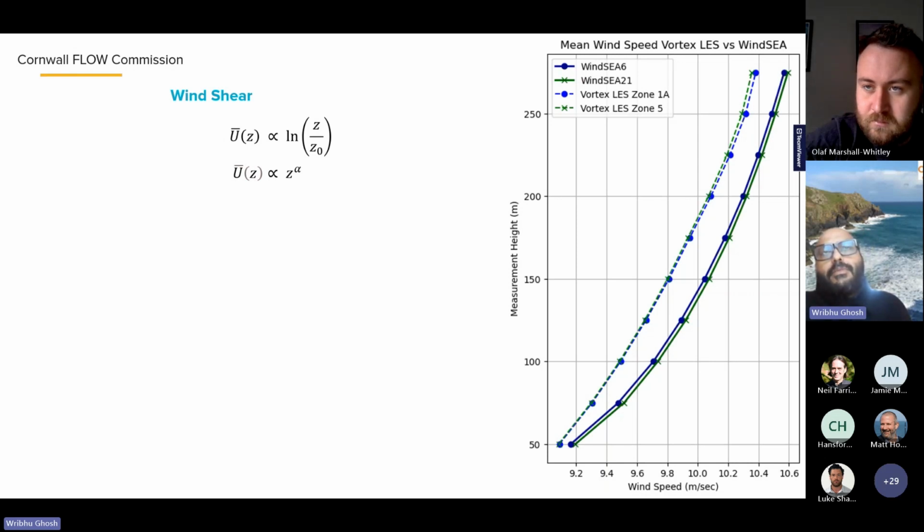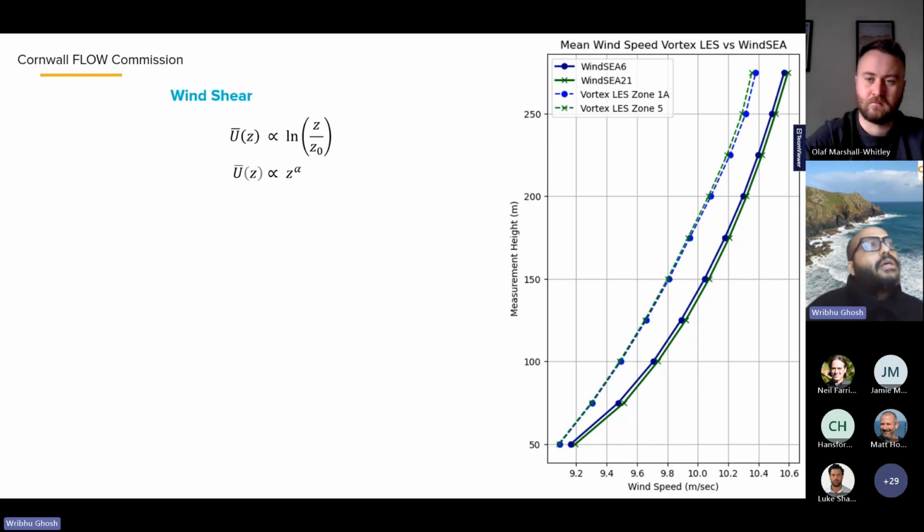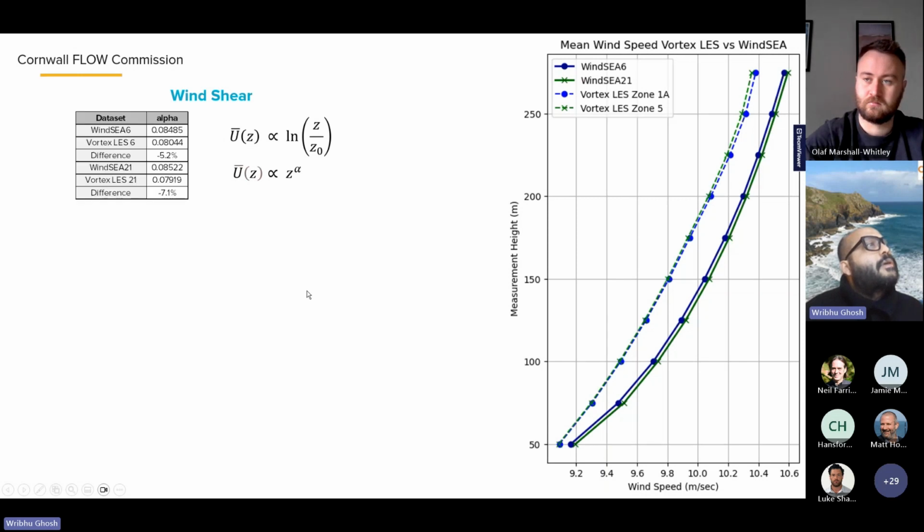A study recently reported that in the North Sea, anything other than monotonic shear happens more than 65-70% of the time when you compute it over a 10 minutes average wind speed, which is much higher than what happens inland. The atmospheric boundary layer is also much thinner offshore, so the modeling of linearity cannot be applied.